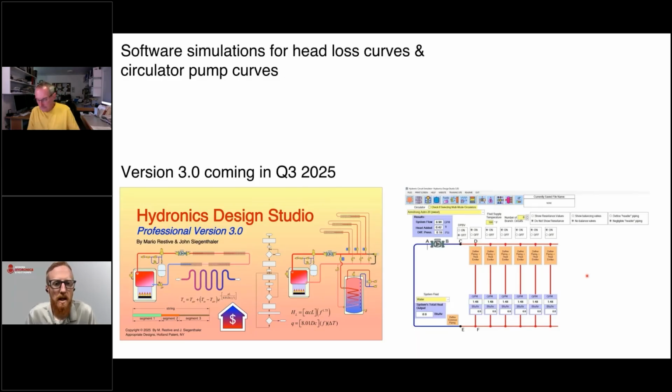Okay. I've got one that was pre-submitted: pump sizing for unknown circuit lengths for retrofits. Well, this procedure is exactly what you need. Unknown circuit length, so we don't know the circuit. If you can get access to where the circulator is, build this test apparatus, put it in there, and go through that procedure, you can create the circuit head loss curve for that circuit.